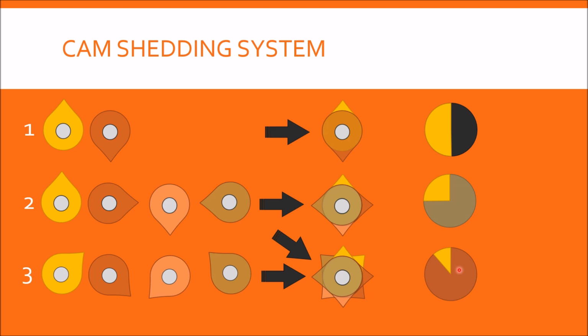So over here I have just mentioned that increasing the cams limits the time available for the camshaft to impart the motion to the frame, and reducing it further than the 45 degree will not help to effectively raise or lower the frame or give it a dwell time. That is why 8 frames is the limit for our cam shedding system.